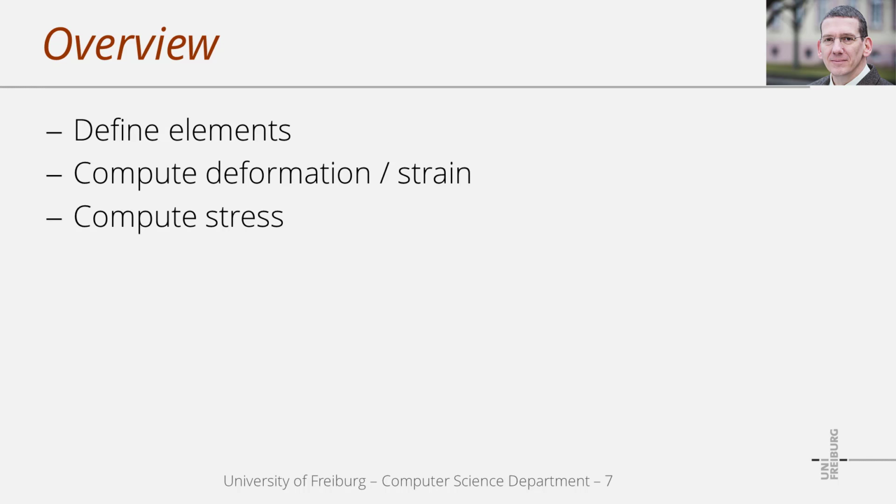In the next step, we compute the so-called stress of an element. This stress is typically governed by the amount of deformation and by the stiffness of an element. On one hand, elastic stress grows for increasing deformation. On the other hand, stress also depends on the element's stiffness. If we have two objects with the same deformation but different stiffness properties, then larger stiffness causes larger stress.